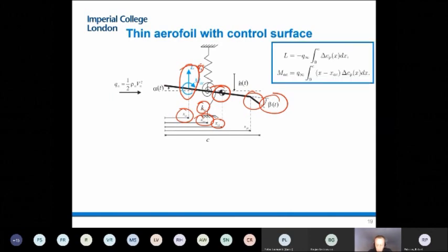And then if I wanted to compute forces, what I will need to do is to link the forces to the distribution of pressures that appear on the airfoil. So typically, if you took an airfoil and you look at what's going on top of the airfoil, you will see something that looks like this. This is the distribution of pressure. Normalized Cp means the pressure on the airfoil divided by, again, 1/2 rho V squared, the key magnitude that appears everywhere.